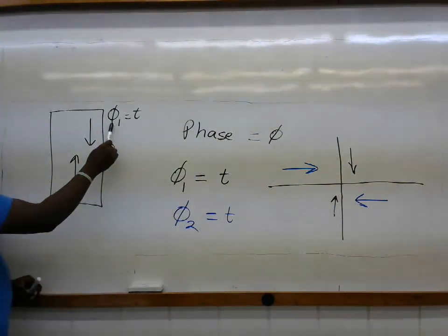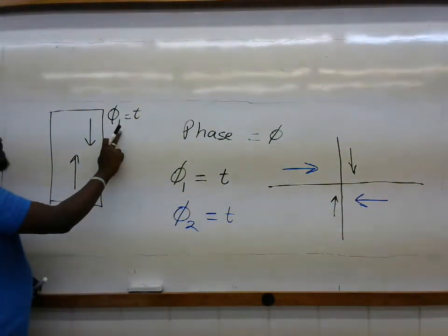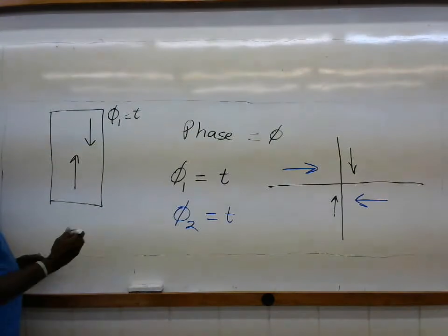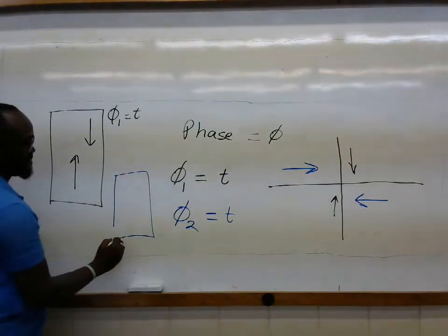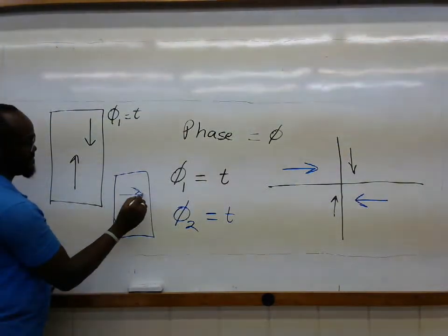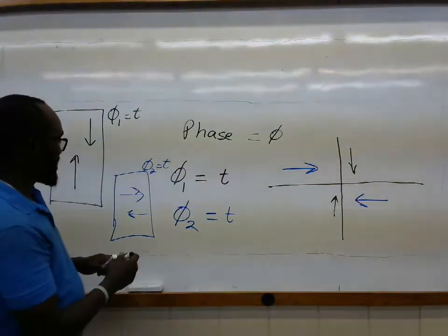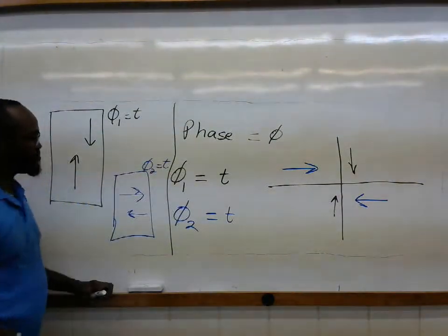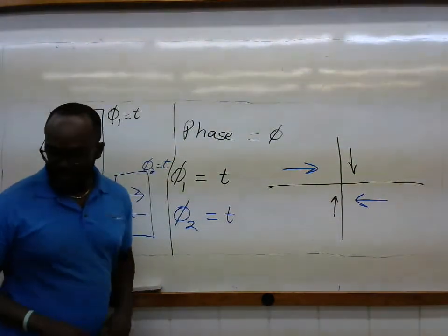So phase 1 would be like this, with the arrow showing the directions of the movements with the right of way. Phi for the number of the phase and the time, whether it's 10 seconds, 25 seconds as the case may be. And as you can imagine intuitively, the other phase will be represented by this diagram. Okay, so the phase concept.